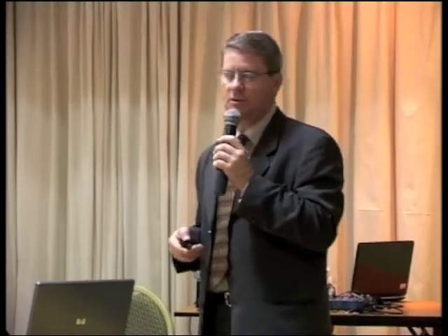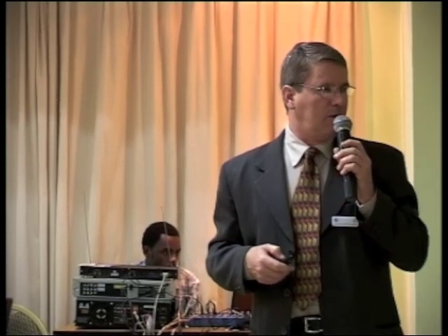realize what will be the tension that the cable will suffer during pulling, and compare it to the values specified by the manufacturer. If we are reaching points just near the values that limit the use of the cable, we can make some arrangements. The more general way is to change the planned route in some place. If these forces are near the maximum force allowed for that kind of cable, we need to maybe find another way for the cable or change something in